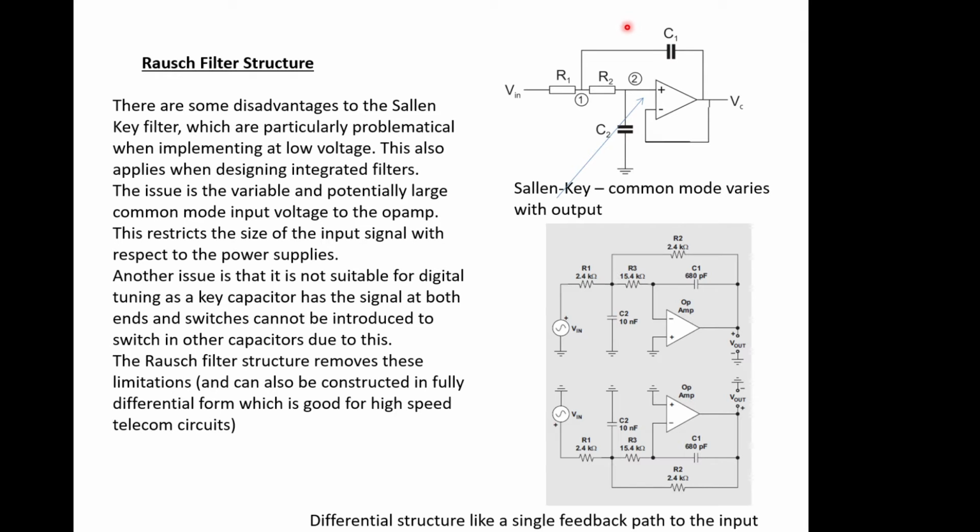So you need to make sure your switching voltage is significantly above the signal voltages, which may not be the case here if you're not referenced to ground at one end. So it's going to be tricky to include a digital switch in this loop here. So that's one thing to think about. It's not a real significant problem, but you never know. One day you might find yourself in a position where it becomes an issue.